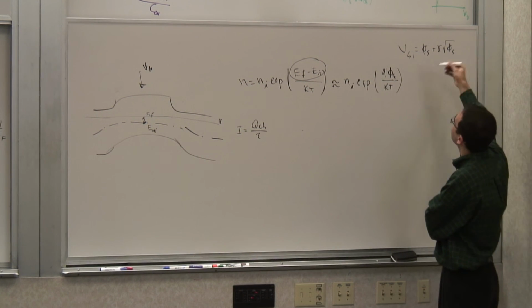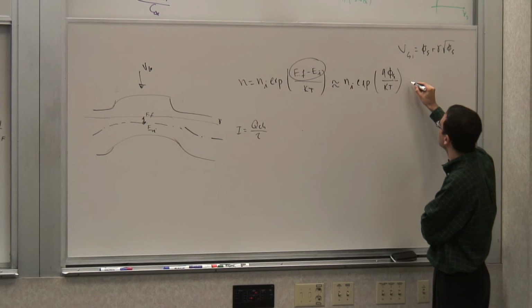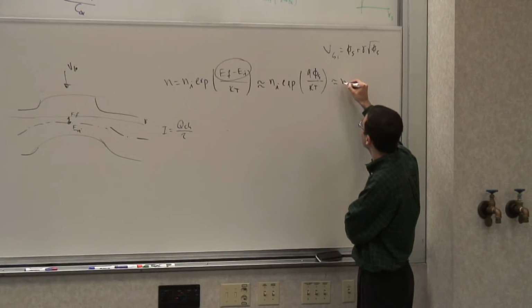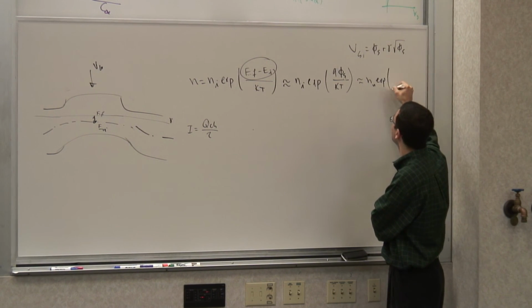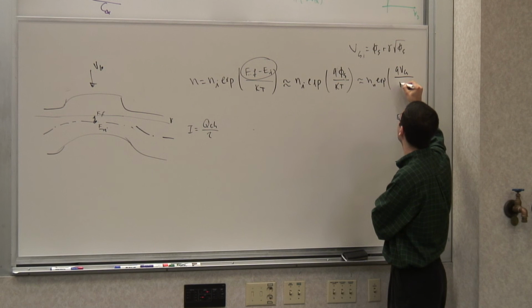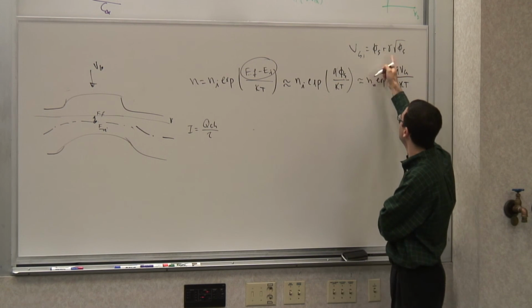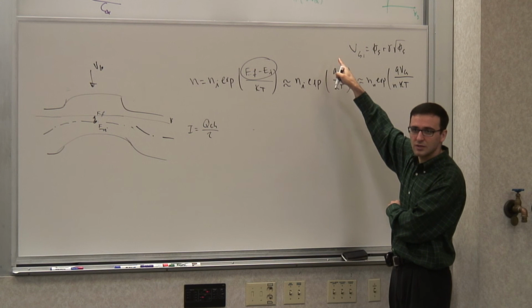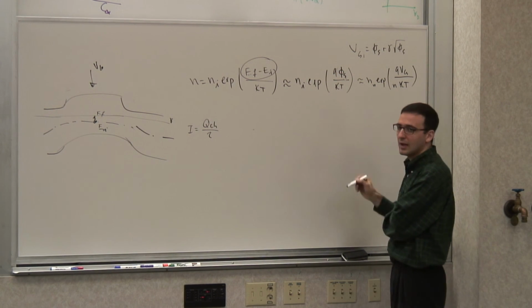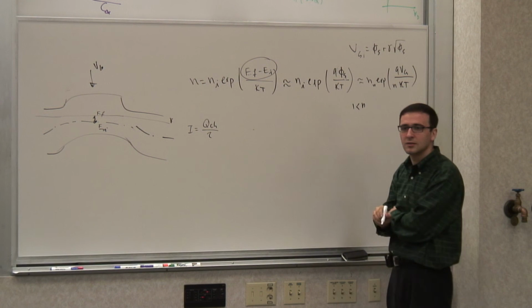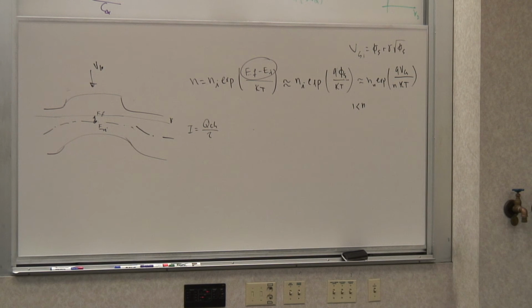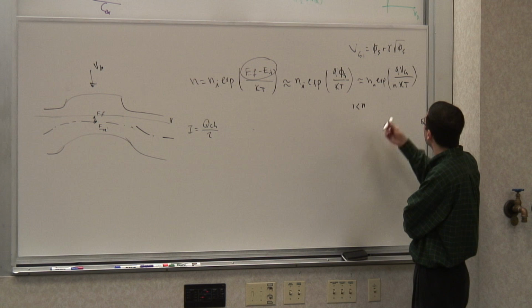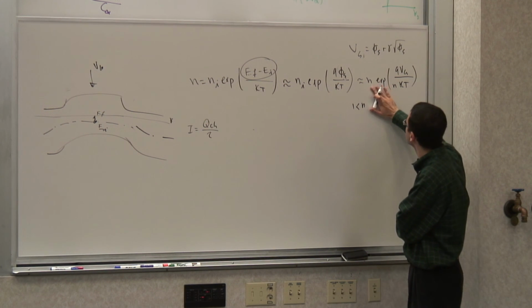Now, you can capture all of that in this relationship by basically saying, well, it's really an exponential, right? So this is a superlinear relationship. So I can relate this to this by saying, well, this is kind of QVG over KT, but then since it is a superlinear basis on that, it's going to be sublinear in terms of Vg, so this has to be a little bit larger than n. N has to be greater than 1 to count that sublinear dependence. In an exponential, you can do that, right? It just changes the slope. Or like log. So what you have here is something like this. And this is Ni.